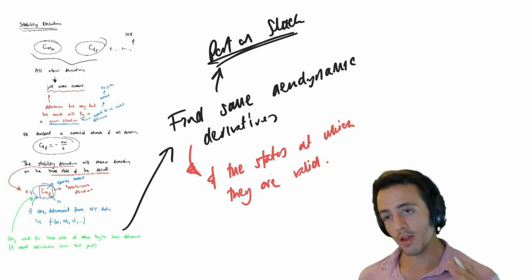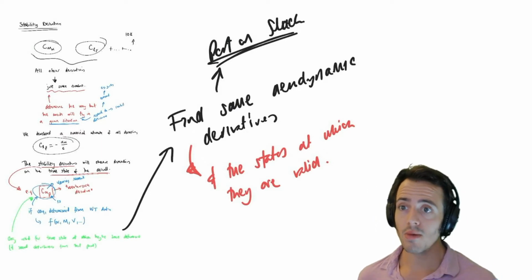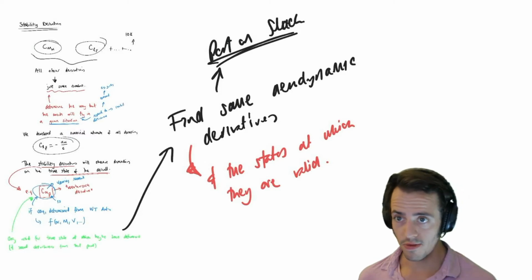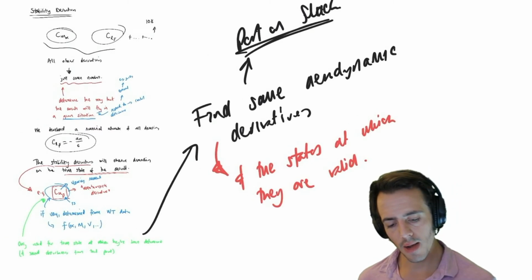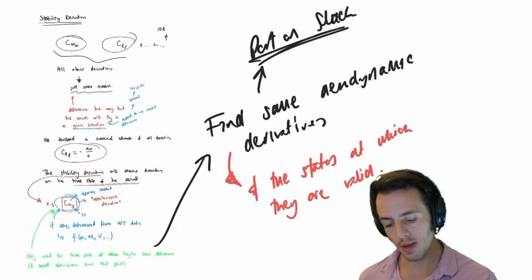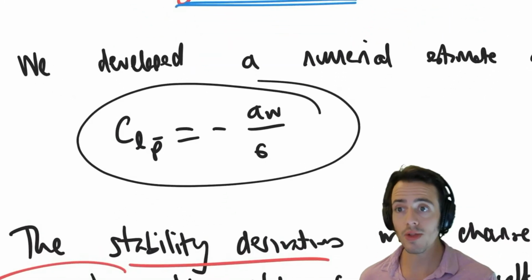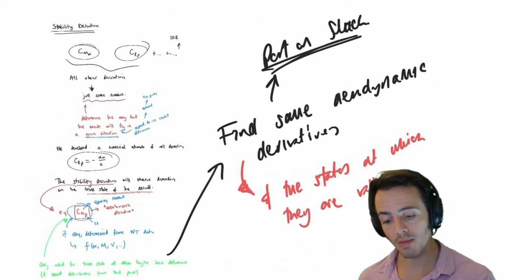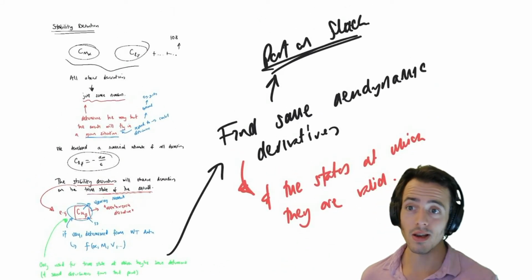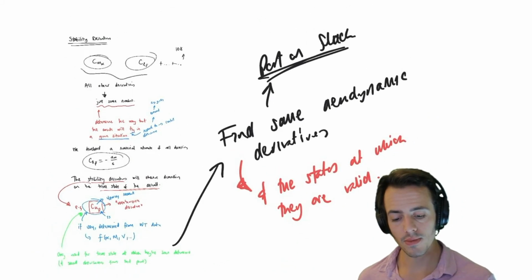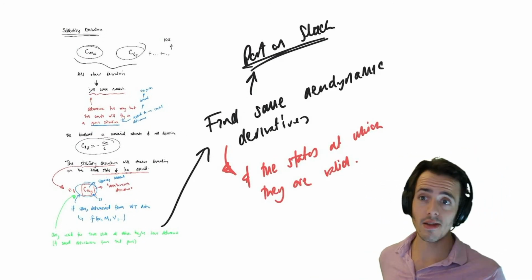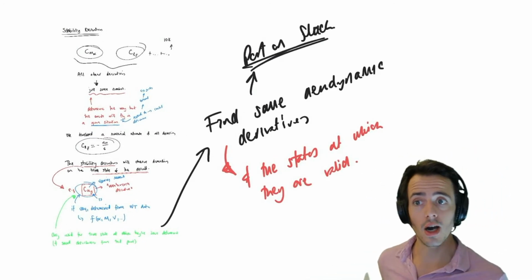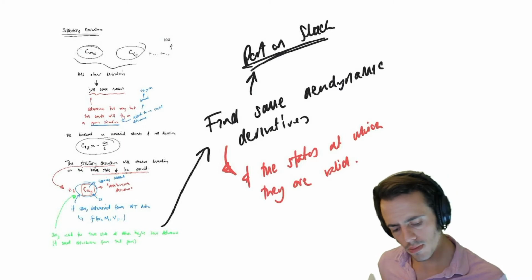So what I'm saying is that you've got to just appreciate these numbers are only valid for the given flight state of the aircraft. And although we could look at some simple approximations here for, say, roll damping, to determine the actual full sets of derivatives, and there are many of them, we need to look at things like wind tunnel data, flight test data, and higher order numerical techniques.